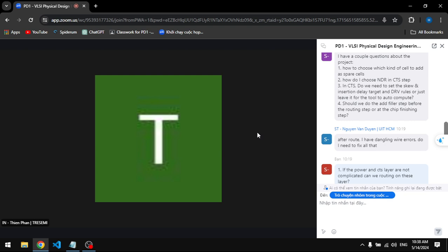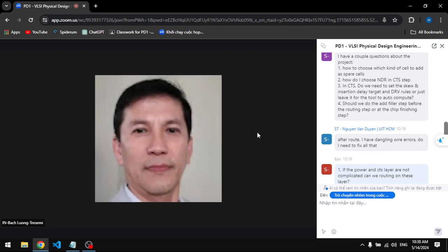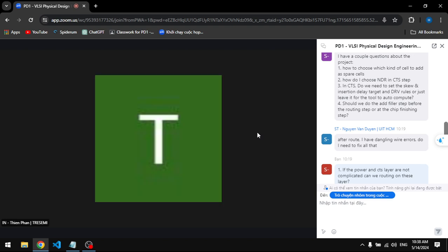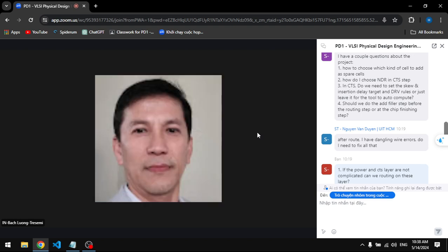So I could suggest, review the power, make sure it's created cleanly. And then if it's not the power, if it's on the signal nets, then try to target it. Try route ECO dash ECO underscore fix DRC and see if that tells the router to focus more on fixing DRCs.